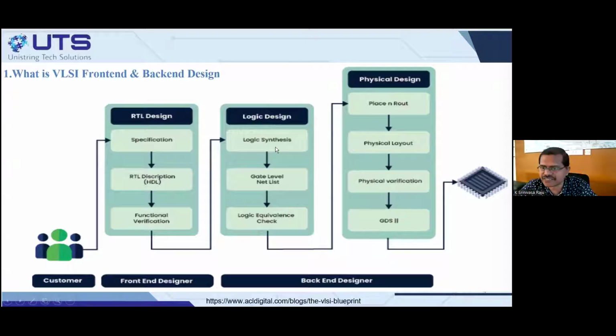Then we do synthesis. In our course, as I already mentioned, our company does VLSI, but we do only FPGA VLSI. We don't do ASIC. So we do not use the ASIC synthesis tool. We use an FPGA synthesis tool, where you convert your VHDL code to FPGA gate level, mux level, flip-flop level. Then again, there is one more simulation. This diagram does not show that.